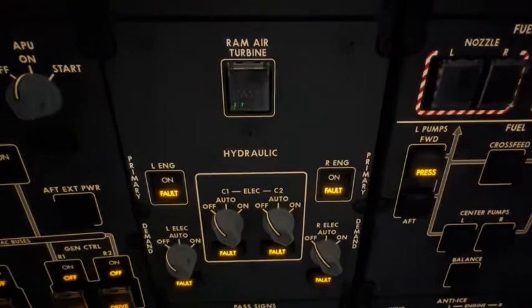Coming back to the 787, one of the most unique portions of the hydraulic system is that it runs on a 5,000 PSI system, unlike the conventional other aircraft that you will see that run on 3,000 PSI. And I know everybody wants to see the RAT. Here we go. This is what it looks like on the 787.